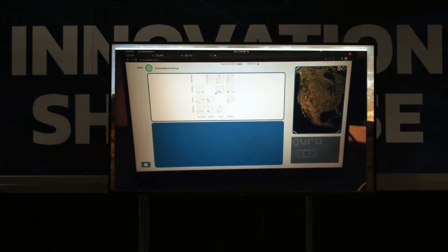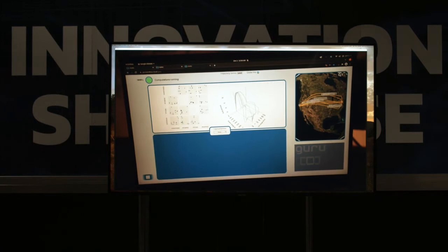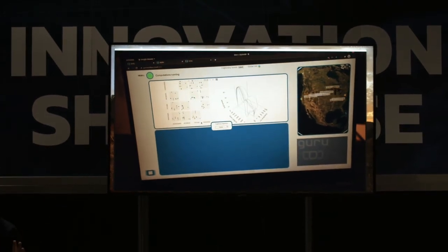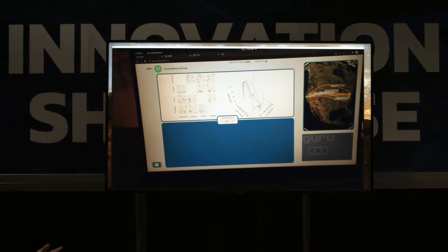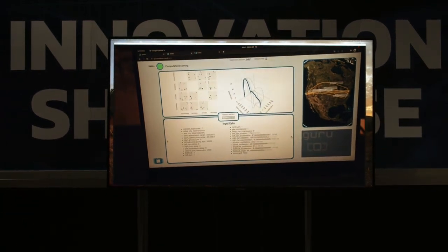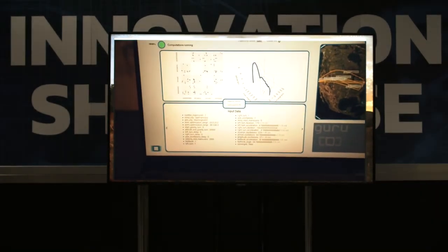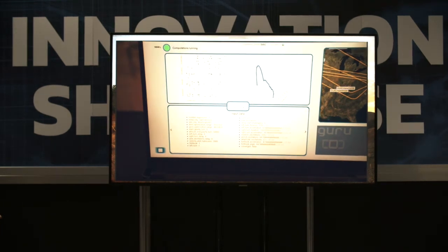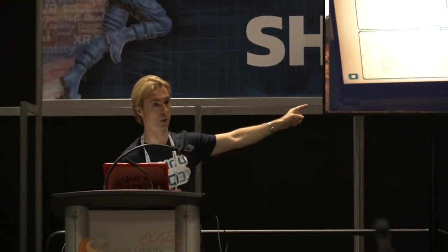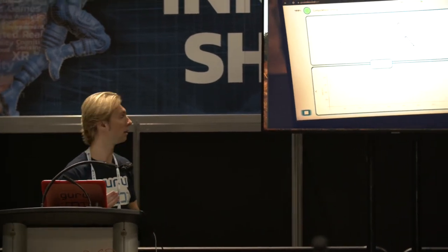So we have trajectory results that were just generated. And on the left-hand side of the screen, you're seeing a clustered view of all the trajectories that were just run. So that's a nice overview way to review a large number of simulations when you run large data sets like this threat space set of trajectories. You have variables in those clusters that show you values for acceleration, pitch angles, durations, and that enables you to select a subset of the trajectories like Dustin has done and plot 3D range plots in both the range plot view as well as in the full up globe view in Cesium, and also generate trajectory reduced data and 2D plots that Guru automatically generates for you, and it gives you a lot of flexible options to generate exactly the types of plots that you want to look at.